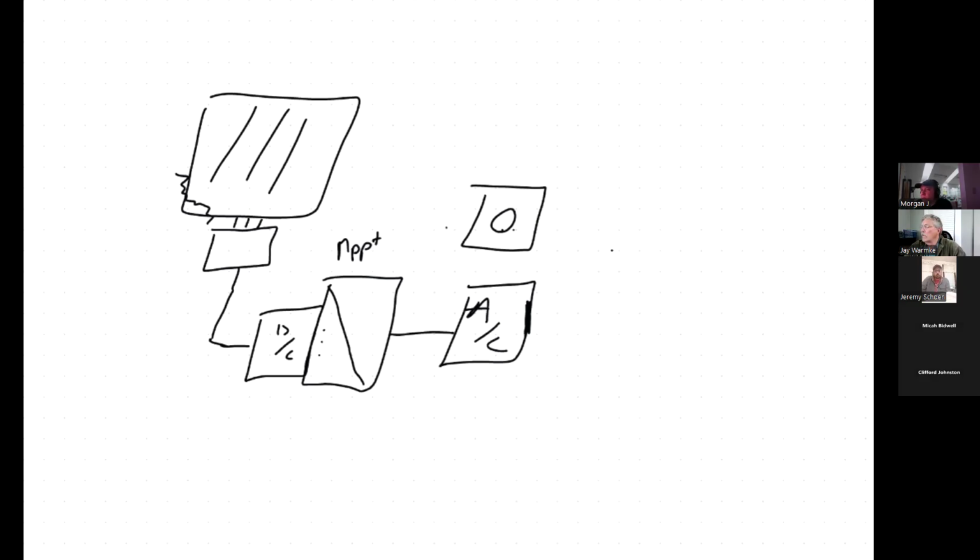Okay. But on that meter, there's going to be a little sign that says, whoa, wait a minute, there's another source of power here. You better turn that off too. Right. So they'll go over and look around. That's why it's within 10 feet, because they'll see it, they'll go over and it says this is the main disconnect for the array. So they turn that off as well. Okay. So now they think there's no power in the building. All right. And this goes out here to the telephone pole,